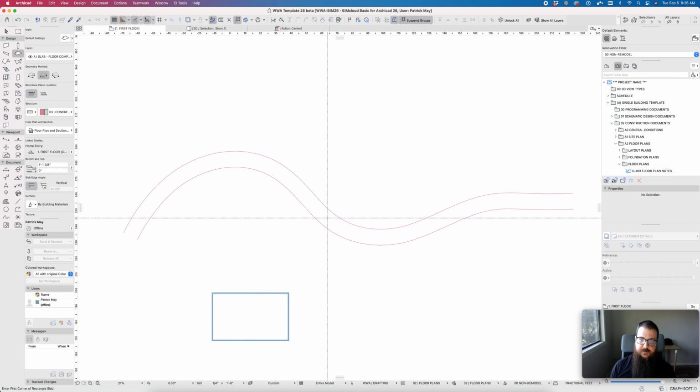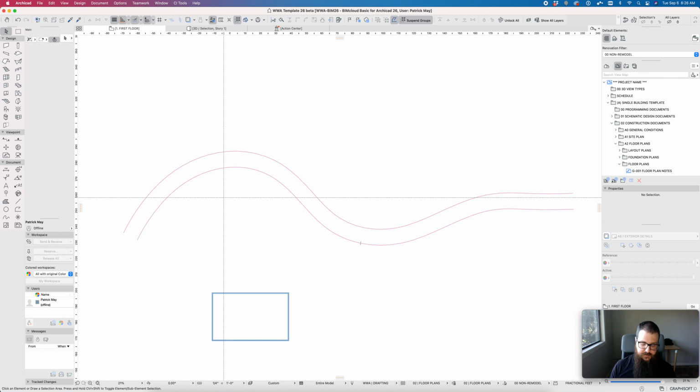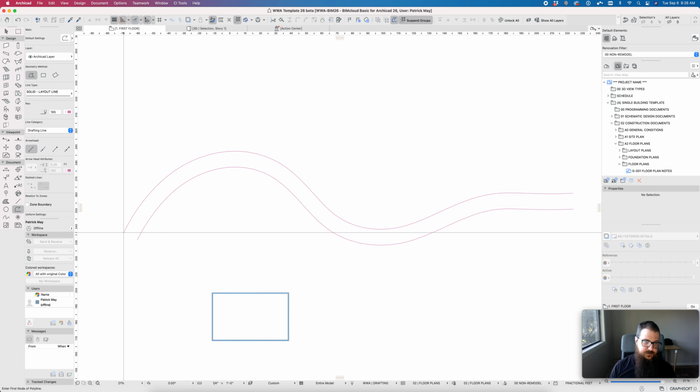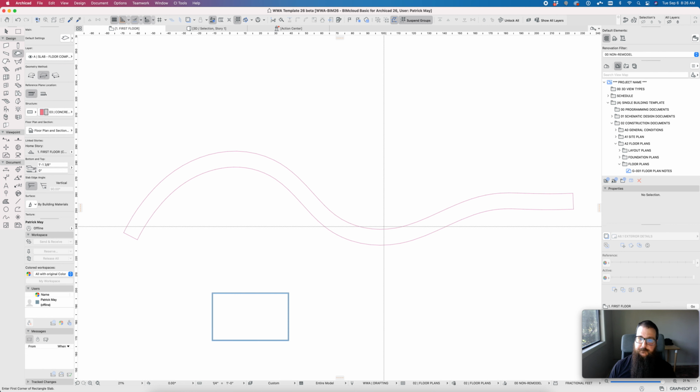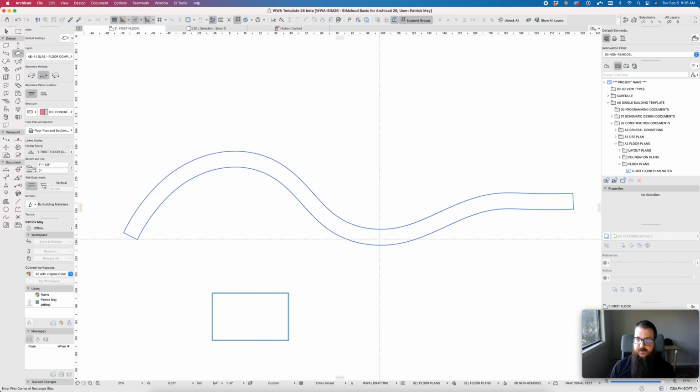Now if I take my slab tool and hold down space, it'll sometimes find the area. Sometimes you have to actually apply end caps onto these. It does prefer an enclosed geometry sometimes. And now I can just hold down space and click on that, and I get a nice slab with a tangential curve. It is possible to create curves with the slab tool right from scratch, but they're very rarely tangential.